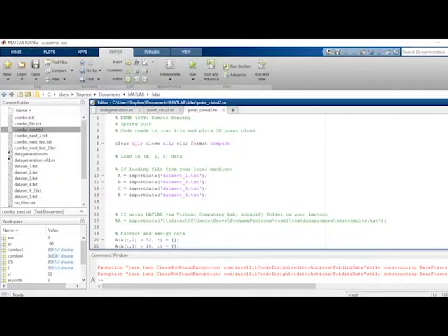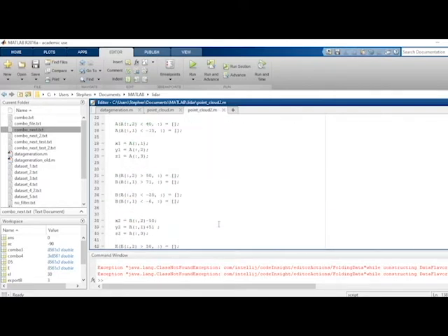The Python script exports a text file with the 3D X, Y, and Z coordinates of every data point. I then import this file into MATLAB using this code here. Using MATLAB, I can combine the individual text files into one point cloud. I can rotate a dataset by 90-degree increments by multiplying the X and Y arrays of the dataset by -1. I did this here.